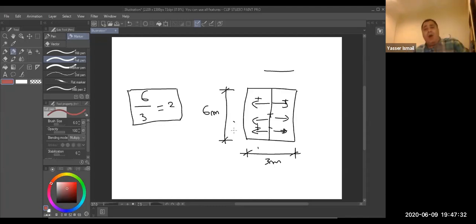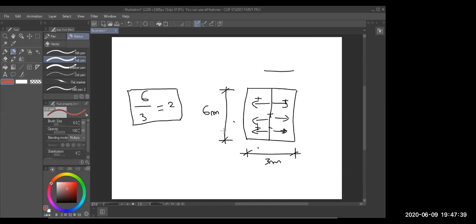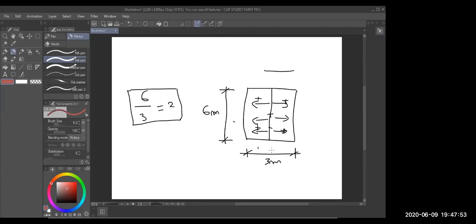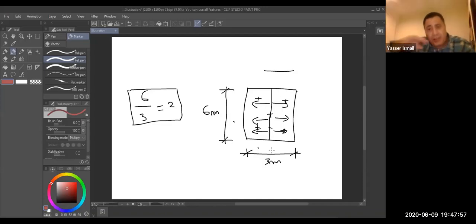So even if you are living on floor number 60, and you have a one-bedroom flat, this bedroom is 6 meters by 3 meters. Does it mean what? You now know the effect of the load goes in two directions to the main beam, and the main beam to a column, until it reaches the next column and the foundation level. This is why we study structure analysis, the effect of the load.